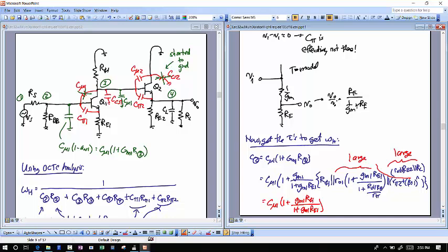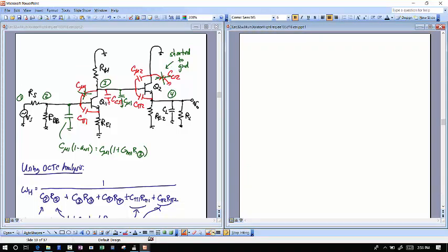All right, and so with C, that's not enough for this. With C2, I need to have an R2. I want to keep the circuit up on that side there, so I just moved on. What's the R2 there? So first of all, do I have any other capacitance I have to worry about at node 2? How about C pi 1? No, I'm not going to worry about that because that's a feedback capacitor. I already determined its driving point resistance separately. Okay, I already covered that capacitor.